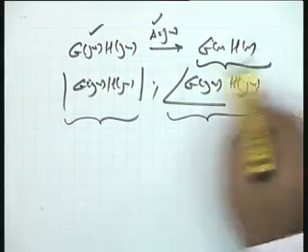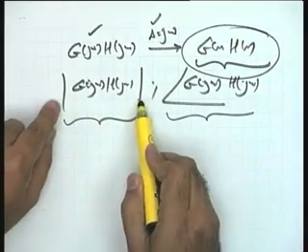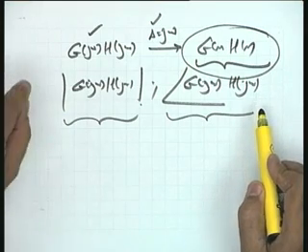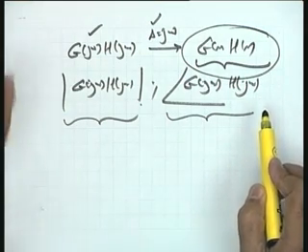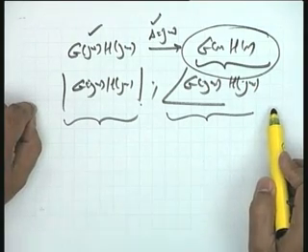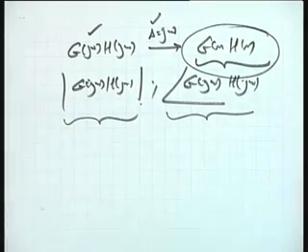So it means actually for this mapping, if the G(s)H(s) function is not available to you, it doesn't matter. You see, I can get these magnitudes and this angle experimentally, and therefore the Nyquist stability criterion can be applied on experimental data as well, recognizing that the open loop frequency response of the system is nothing but the mapping of the positive half of the imaginary axis.